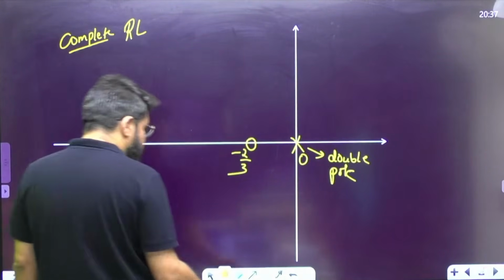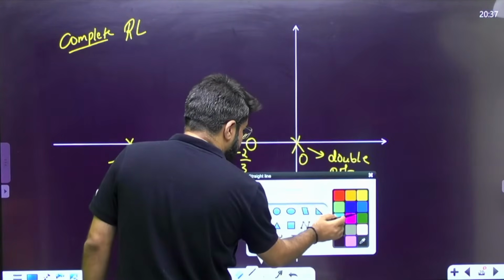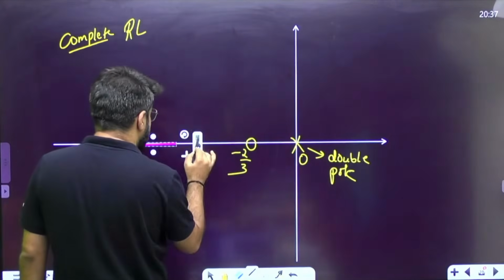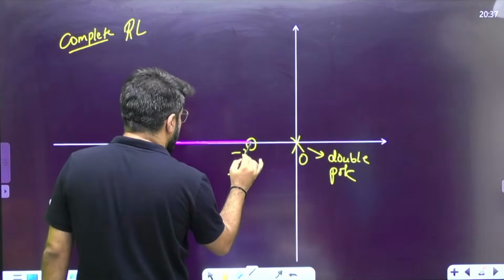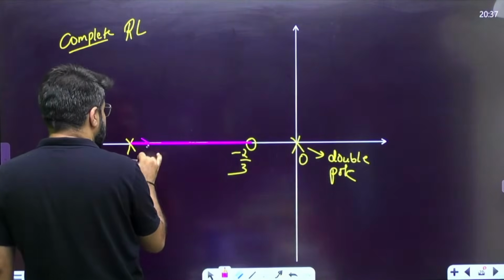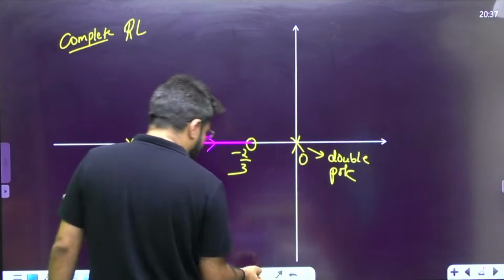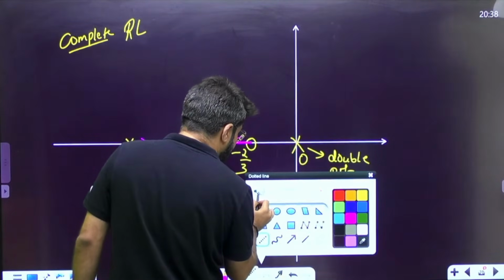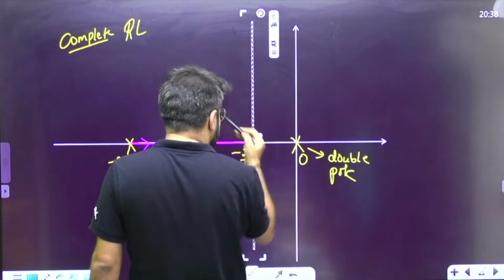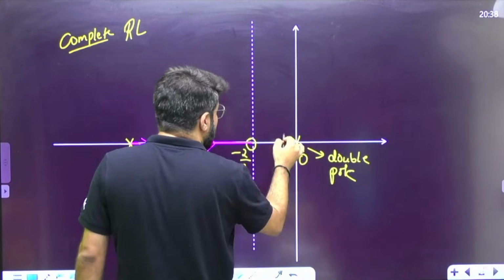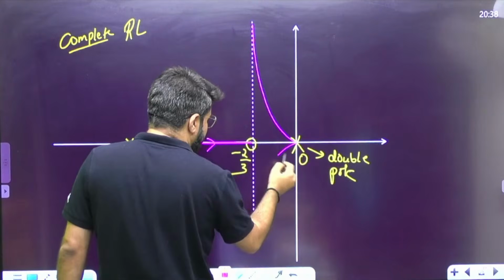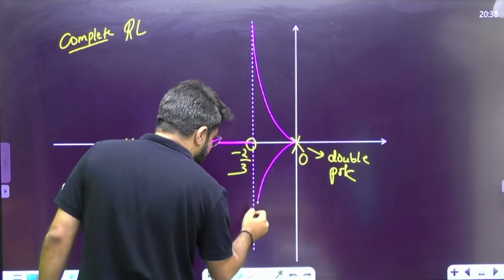What is actually going to happen is, one of the root locus branches will start from this minus 2 and terminate at minus 2 by 3, and I'll draw the arrow as well. This is the story of one of the branches. For the rest two, I'll again bring the asymptotes to the picture. These are the two asymptotes that I have shown you in the previous one. One branch will be tending like this. There is no breakaway point that will come up here, and one branch will approximately travel like this.